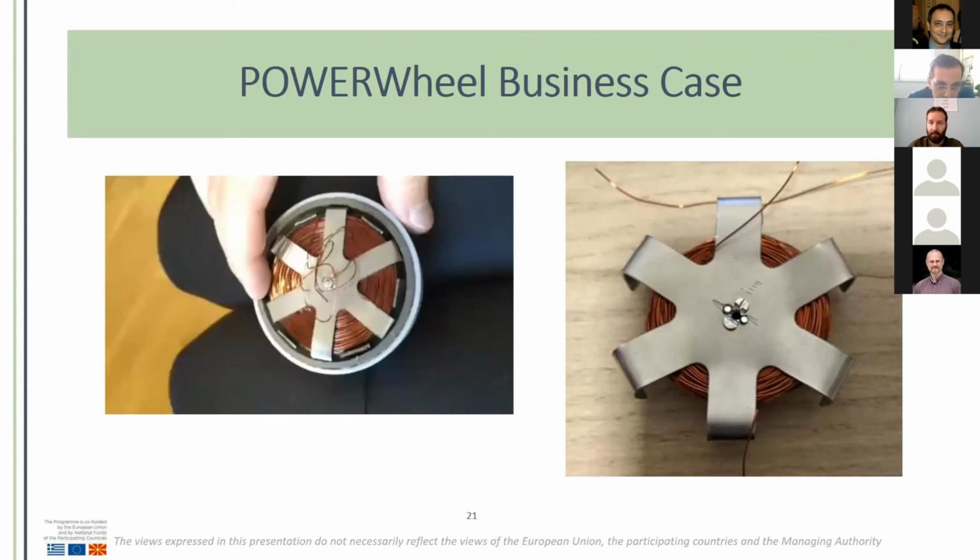So the outer part, this light gray area, is the wheel, and that's 3D printed on a 3D printer. The inner, this gray area, are magnets. We have 6 magnets connected to each other with different polarization. And inside we have the stator, sorry. It's a metal cage with this shape and a coil inside.